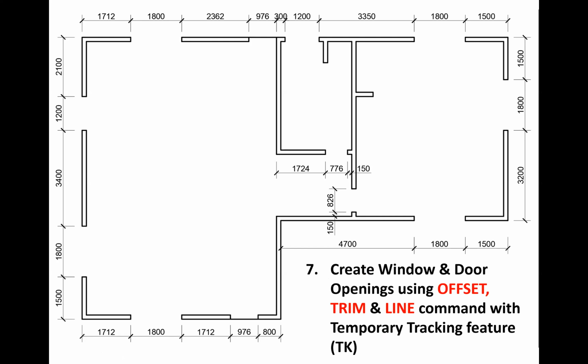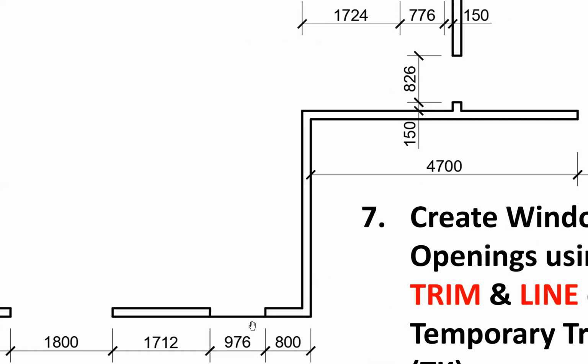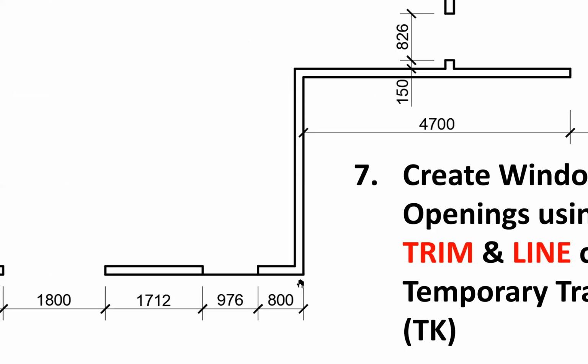All right. So let me zoom in. Well, I don't know if I really need to zoom in because you can see the measurements down here, or I could zoom in, make it a little closer up. So if I were to track 800 and then draw 150, and then later on we could offset. So what I'll start out by doing is just draw one door jamb.